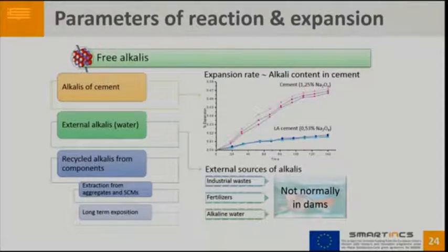But it's very important to take into account that not all the alkalis from the aggregates are available, because they are inside of the big particles, and the alkalis never enter to the center of the aggregate.